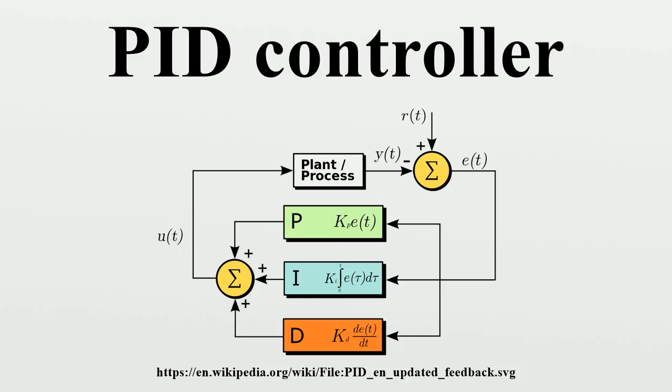PID tuning software. Most modern industrial facilities no longer tune loops using the manual calculation methods shown above. Instead, PID tuning and loop optimization software are used to ensure consistent results. These software packages will gather the data, develop process models, and suggest optimal tuning. Some software packages can even develop tuning by gathering data from reference changes.